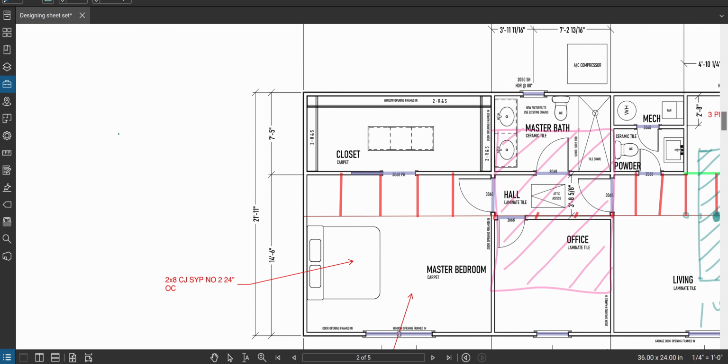If I were to draw a section of the wall, I have an 8-foot ceiling. There's my ceiling line. There's my 5 feet of attic. There's the peak of my roof. There's my foundation. The wind's going to blow on this from the outside, right? And if I don't have support right here, this thing is going to buckle inwards like this and break and fail. We don't want that. That's what we're trying to avoid, right?